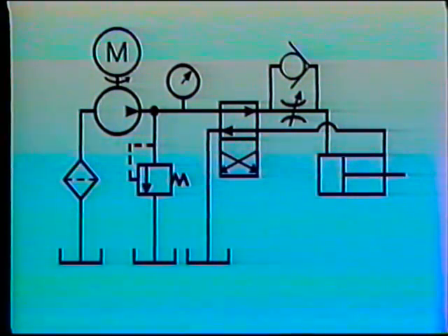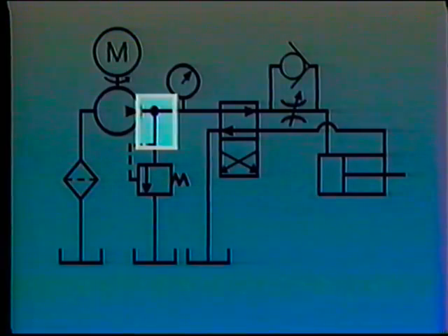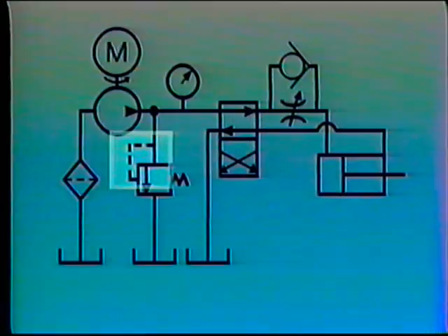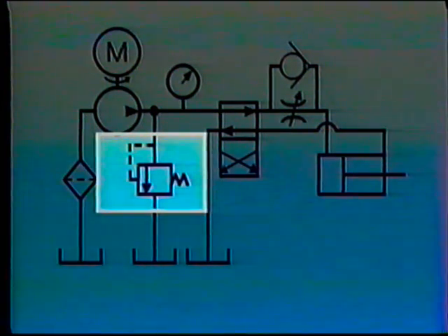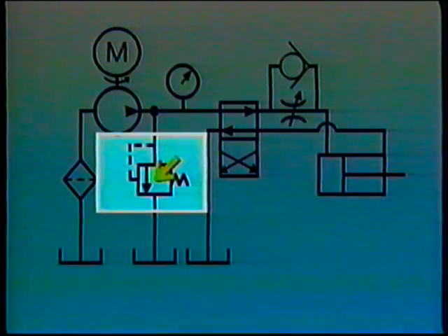The lines represent the system's piping, some of which cross without joining. For lines that do join, a dot can be used to indicate the connection. Pilot lines used to shift spools and other movable members are represented by a dashed line. This is the symbol for a pressure control valve. It includes a representation for the normally non-passing spool and the spring which biases the spool in place against the end of the valve. Notice the pilot line and the symbol for this valve.